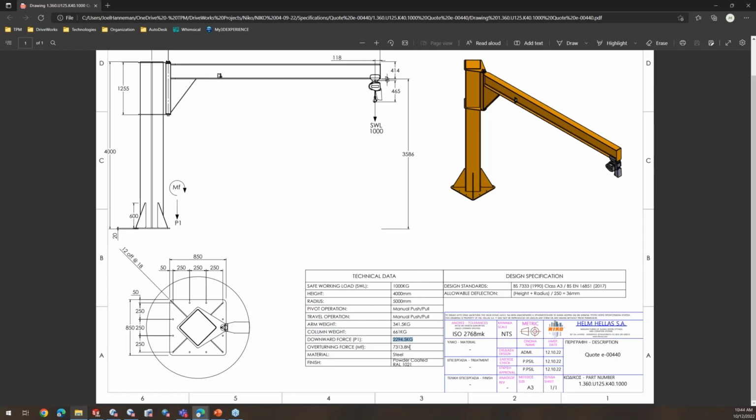Back to the overall workflow: the user enters stuff into the form, DriveWorks pushes data into SOLIDWORKS, but this data in the drawing is dependent on values that only exist in maybe sub-assemblies or components. So what we had to do is export mass properties from various components, bring them back into DriveWorks, have DriveWorks do some math, and pump the result of that math into the final drawing.